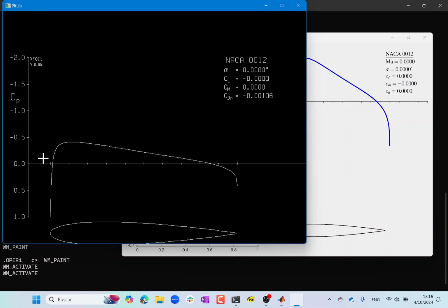So if this is equal to minus 0.5, that means P is equal to P infinity minus, let me just write it as half times half of rho U infinity squared, right? I put this as half and half, but not as a quarter, because this is going to be used as a blob when we are plugging in that. So this is P infinity, right?